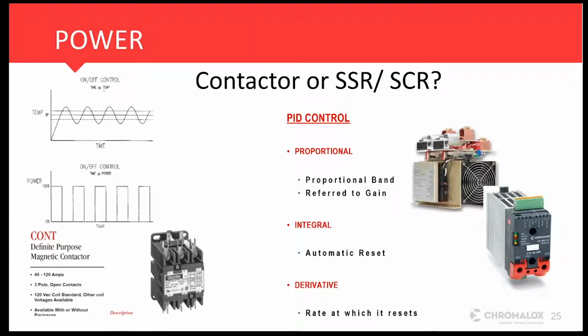So the very first question is pretty simple. Are we talking about a contactor or an SSR or an SCR? Contactor is very simple, on-off control. You want a longer cycle time so the mechanical components of it don't get worn out. And just as far as the CT world goes, if you have an end user who's interested in tossing a contactor or 2 into a quote just to get it done, I think that's a good opportunity to sell these contactors.